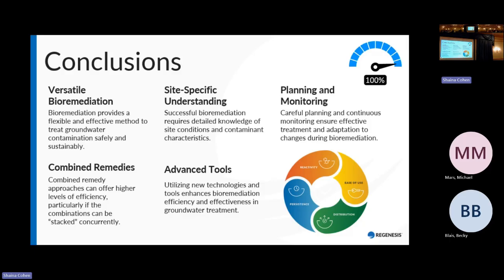I will say I love when we get microbial data on the front end, but it's not super common that I get that, and I don't get to dictate that it happen. By and large, for petroleum sites, I think it's generally agreed amongst the industry that those bacteria are present at sufficient quantities. You can certainly take samples and assess that, but people typically don't, because those microbial analyses are not cheap, and enough literature suggests it's probably there.